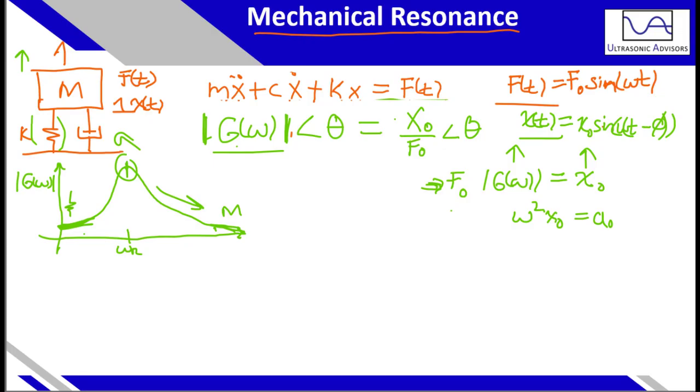Because as I described in the previous slide, if you have low damping, a lot of lubrication, then for a certain input power, you'll be able to achieve a lot more stored energy. It'll take a lot more amplitude for that dissipation to occur.